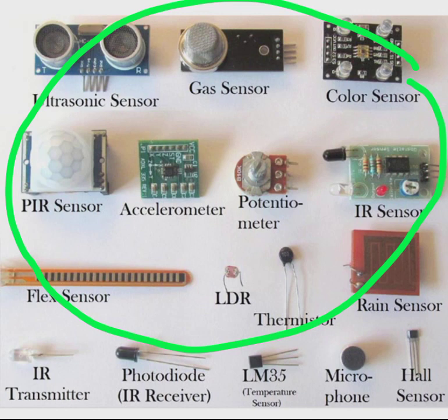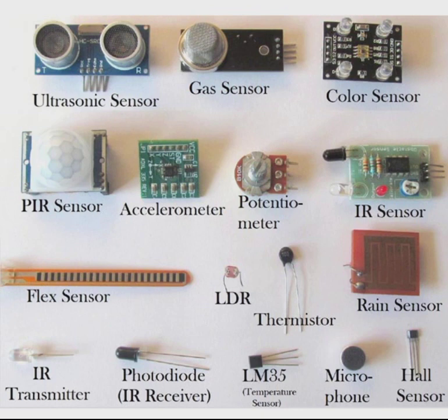After they perform their function they can be integrated with embedded electronics such as a microcontroller, a very popular board known as the Arduino 8-bit microcontroller. All of these produce analog output, and that analog output is then received by the microcontroller board. The first function of the microcontroller board is the inbuilt ADC. If it has one, it converts the analog into digital, and then the microcontroller processes that digital signal.